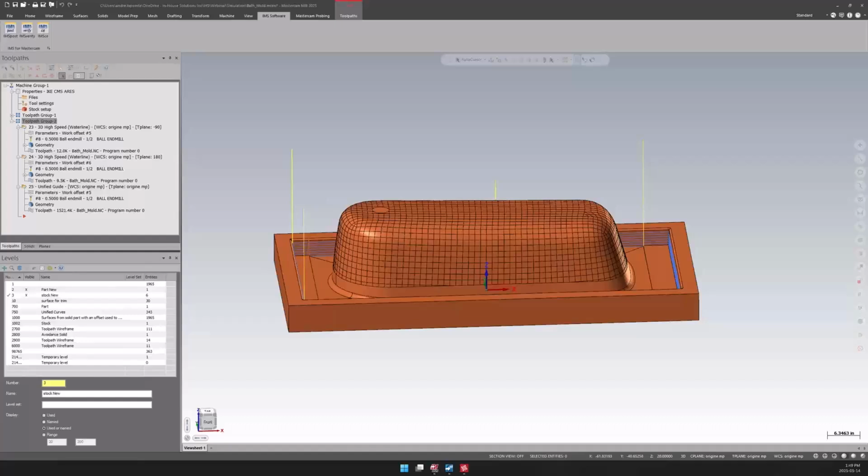Sorry, Lee. One thing that I may add that we haven't talked about yet, sometimes people are interested in knowing that those two simulation options with G-code simulation, whether it's the Simco Edit with the backplot or the Verify, or the IMS CE, are able to simulate macro commands. So if you have some specific macro or sub-programs that you're running, it all supports that. If you run a program with a couple of sub-programs in it, they will jump back and forth and execute in the simulation without any issue.